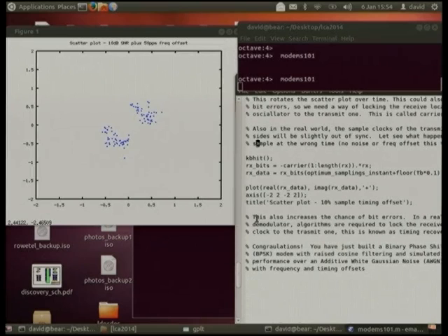Now also for a real world system, the transmitter will have a D to A converter with a sample clock. It might be clocking out samples at a million samples a second. The receiver will have an analog to digital converter that's sampling the signal at, say, 1 million samples a second. But those clocks are at two different sites. They're running at different frequencies. It's just slightly off. There'll be different temperatures and things. So you'll see one will be a little bit out compared to the other.